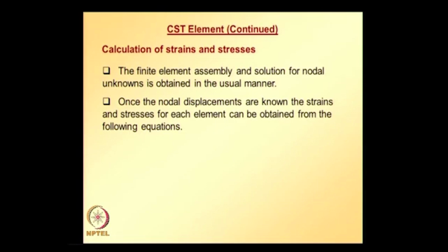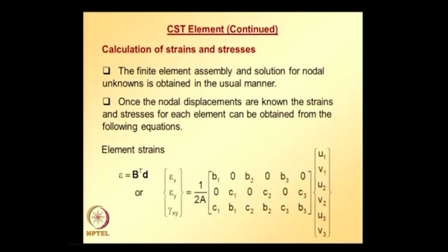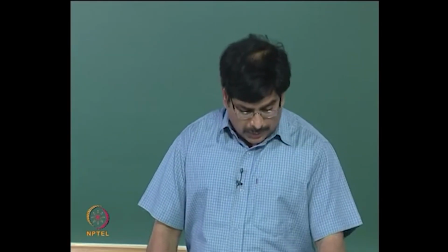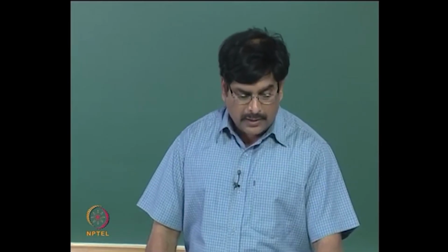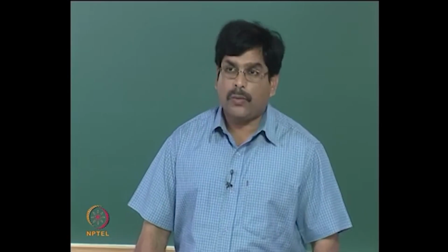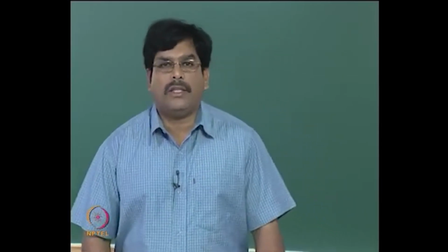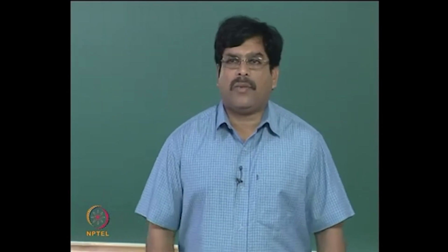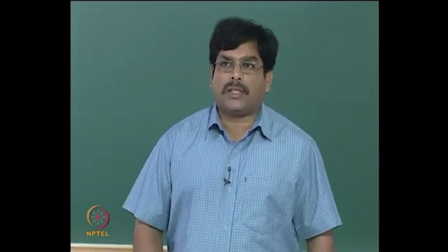Once the nodal displacements are known, strains and stresses for each element can be obtained from the following equations. Strains can be calculated using this strain displacement relation, and once we know strains, we can calculate stresses, which depends on whether you started out with plane stress assumption or plane strain assumption.